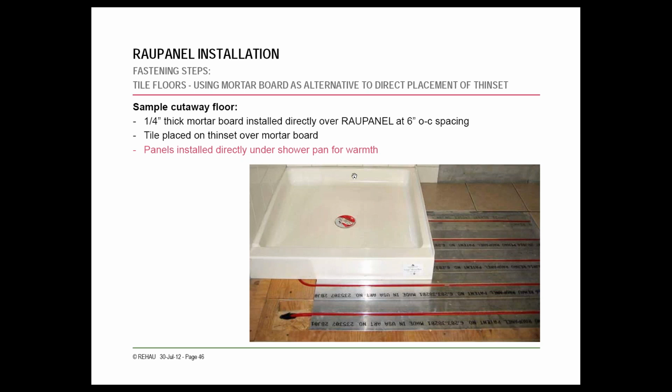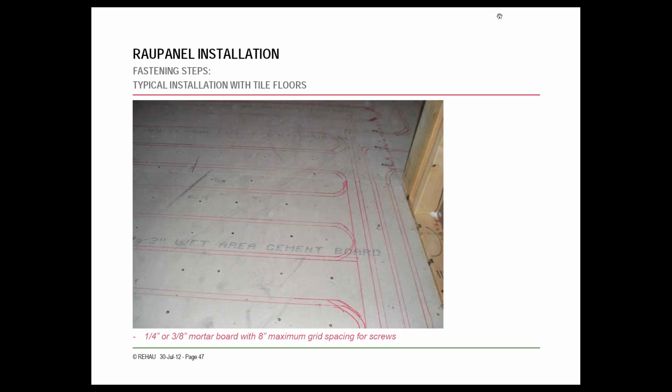Here it's showing them directly beneath the shower. No problems there. You can install this, as I'll point out shortly, on walls, ceilings, floors, wherever. Another good application for this system. In regards to bathrooms, with this tube or any tube, you want to avoid getting too close to the wax ring for a toilet. Keep it about 10 to 18 inches away from any toilets.